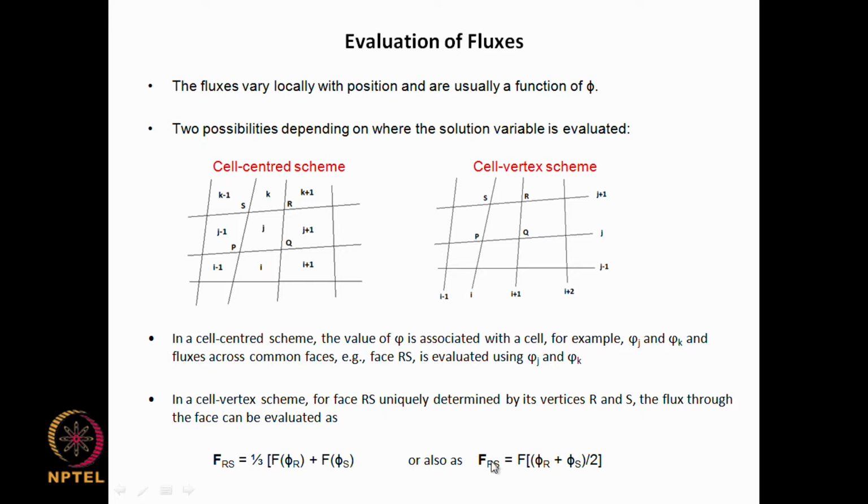So, you can say that instead of that I will take an average of phi R and phi S, and use that average value of the variable here in the flux expression to evaluate this. So, you can have either of these formulations.